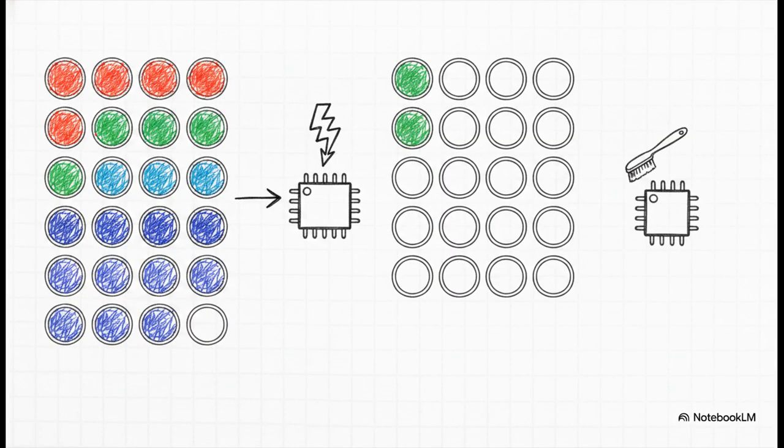And then sometimes the module is on, but a specific color, say the entire red or the entire green channel, is just totally gone. When one color channel fails, it almost always means the data signal for that specific color is short-circuited somewhere, or, once again, that trusty 74HC245 IC has a fault. Finding and cleaning that physical short on the board or swapping out the IC is going to bring your full color spectrum right back to life.